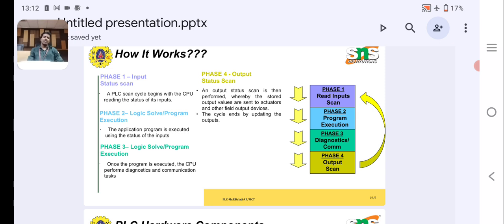The cycle scanning time of a PLC, its response speed, is determined by the CPU used, the size of the program to be scanned, the number of input outputs to be read, and system functions that use a greater number of slower scans. As an illustration, the Mitsubishi compact PLCs have a program speed of about 0.05 microseconds per logic instruction. The more complex the program, the longer the cycle time will be.